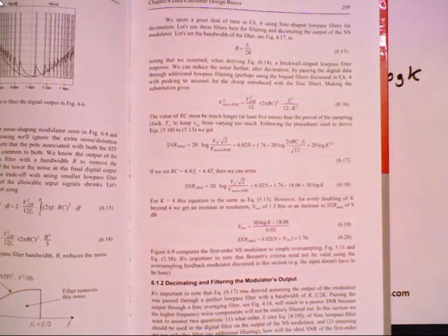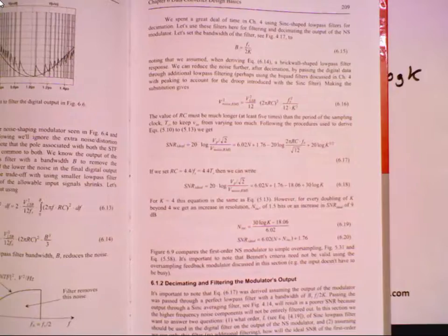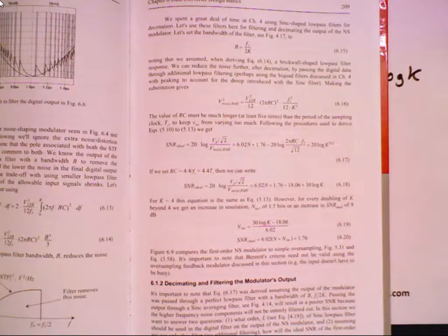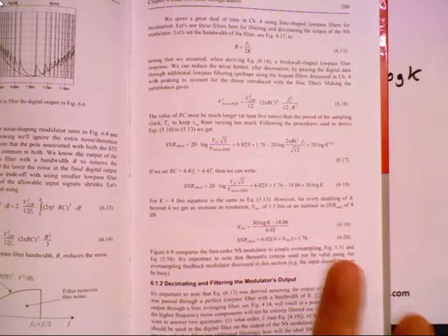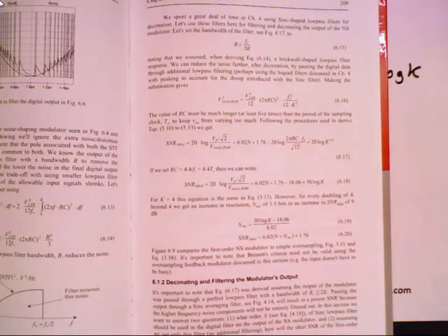Here's the thing, if you have a really large RC, then you're not going to get much variation because you're really filtering it a lot, right? And if you keep your input signal, I should qualify that by saying if you keep your input signals slow, okay? Because if you keep your input signals fast, then it's going to vary a lot anyway. So there's a lot of gray area. Did that make any sense?